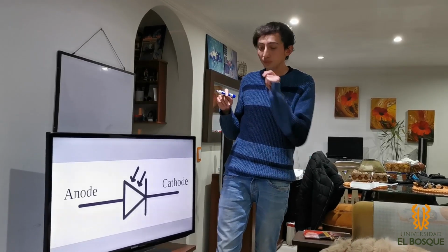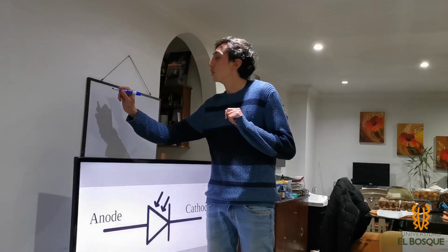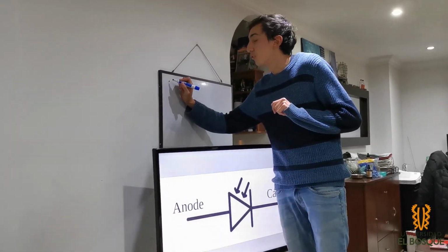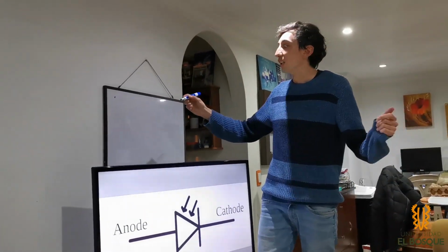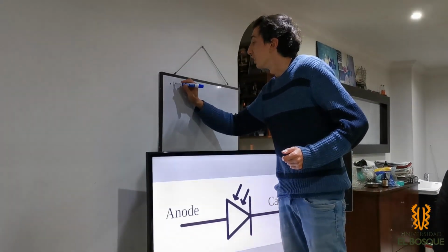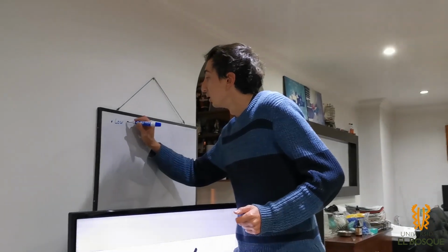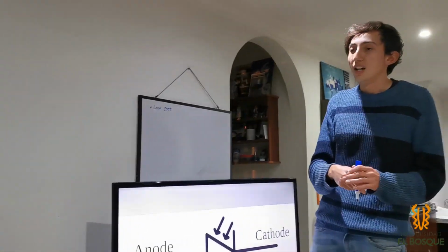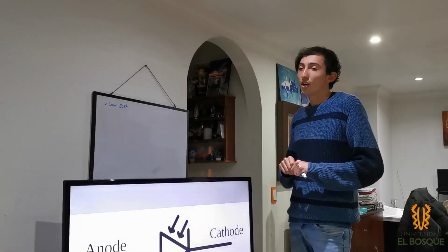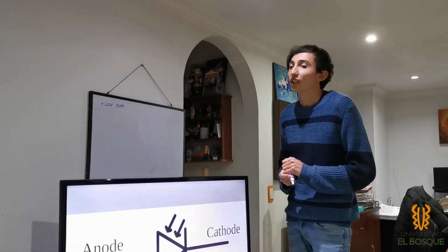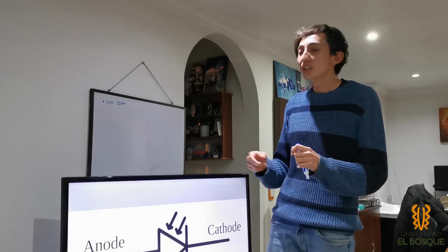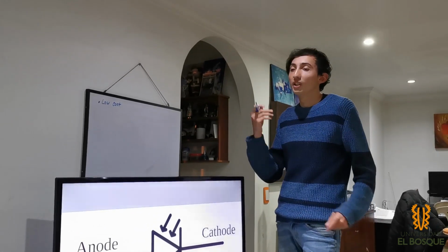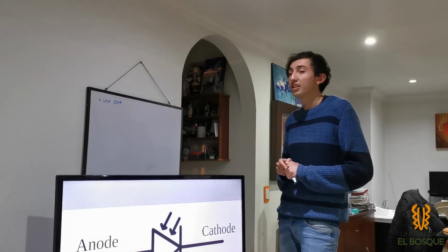It's important to point out a few of the benefits of using photodiodes, like their low cost, and that they are near-IR photodetectors. Excellent linearity in output photocurrent over 7 to 9 decades of light intensity.